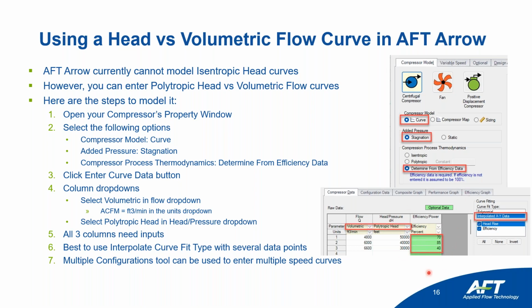The efficiency data, we need that once again to figure out that polytropic constant, and also to figure out what the discharge temperature is based on the efficiency and the pressure rise across the compressor, or pressure ratio across the compressor that we figure out.